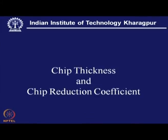We have seen that we can measure hardness, critical adhesion, then tribometry, all sort of thing. These are all characterization, but even after that we must go for the actual field test. That means, if it is a cutting tool, then it should be put on a machine tool in some machining engagement.